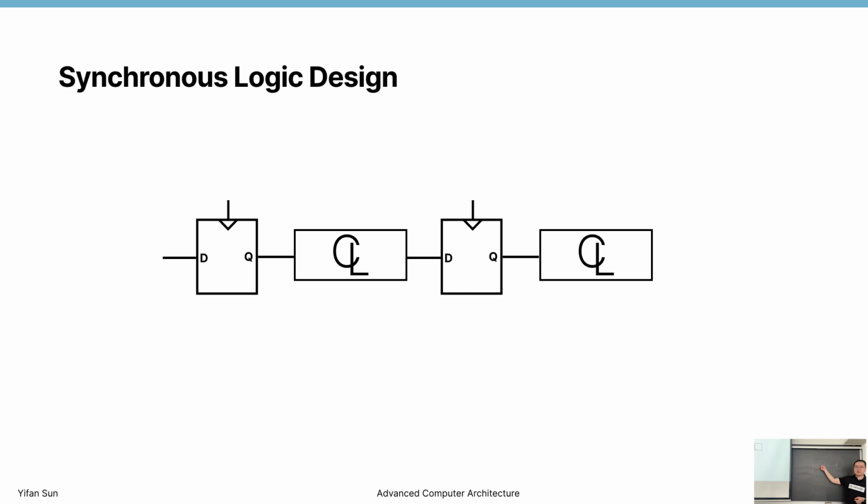so basically it takes some time to fluctuate until it arrives at a stable state. Then with experiment and calculation, you know how long it takes to finish one calculation. So for example, if one gate takes 0.1 nanosecond to finalize its open and close, then if you want to set 1 nanosecond as the clock period, you probably can only have 8 levels of gates.